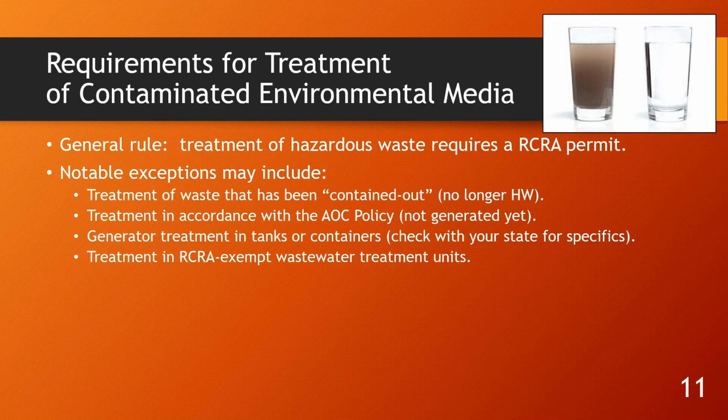Generators can also treat in tanks and containers and in wastewater treatment units under certain circumstances. And they can also get authorization under RCRA corrective action. You can get authorization for a treatment unit or CAMU, corrective action management unit. This is the RCRA corrective action version of giving you a permit without making you go through a permit process.